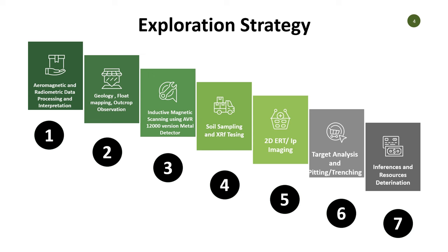Now, soil sampling comes in different patterns. You can start soil sampling in different stages. You can put them in a grid, or put them in a grid in such a way that they are detailed. If the soil sampling is well done, it can give you an interesting soil anomaly, which we've done in some locations, and we were able to find this. Otherwise, you can do a 200-meter grid, then it comes down to 100-meter, possibly down to a 50-meter grid. So this has always been a good one.